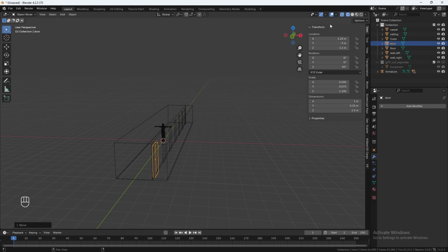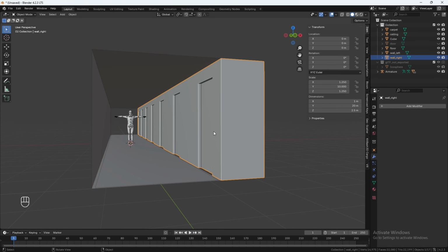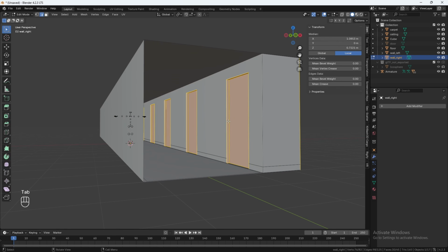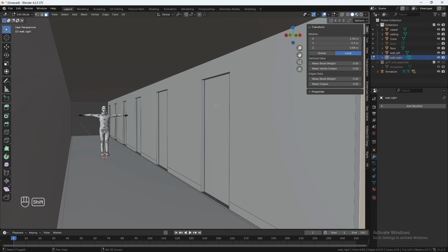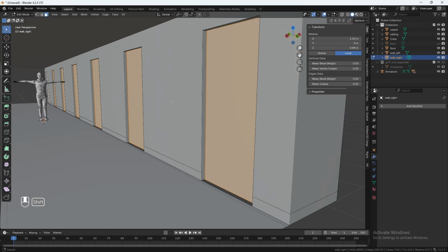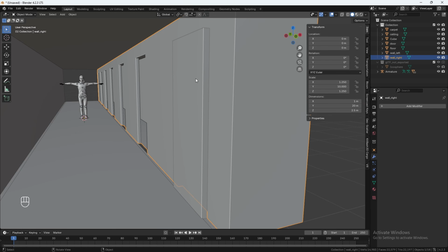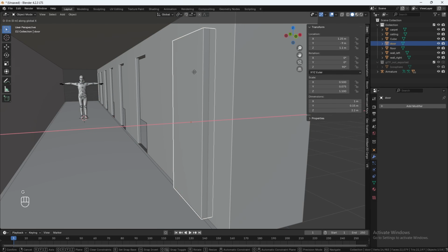This is on the -Y view. Let's hide our door, and let's click on our right wall, go into edit mode. Let's select these faces here. So use the face select tool. Select this face, hold shift, and select this face, this face, this face. Okay, they're all selected. And then just hit X, delete faces. Now bring back your door, and we'll just move the door slightly inwards.